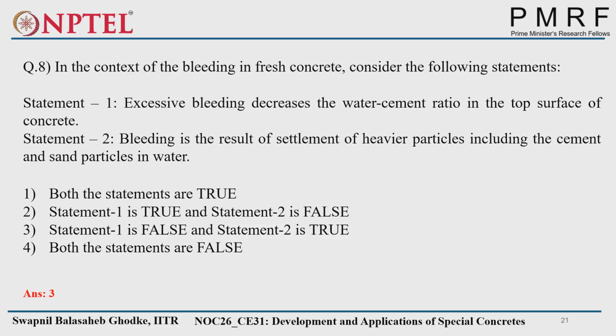Yeah, that will help, because water and strength have a direct relation. If you reduce the water cement ratio, the strength will increase. But at the same time, you have to maintain the same flowability, so you have to add admixtures. Suppose for one project you require M20 concrete, and for that you require a 0.4 water cement ratio, but you are using 0.3. You'll get high strength concrete, obviously, but there is no requirement for that. Then you have to think about that, that high strength is not required.